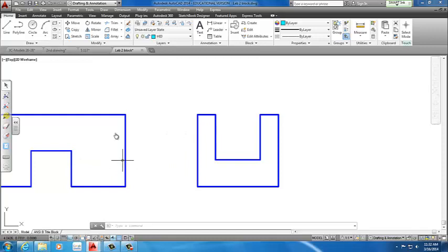It saves you time. All I need to do is use the line command. So you type in P-edit. I click my mouse over here to this line. You select line, enter. You type M for multiple, and then select that line, enter. You see all of the green dotted parts of that line, this will ensure that it's following the center line. Do not skip any. There's 1, 2, 3, 4, 5, 6 perpendicular parts.